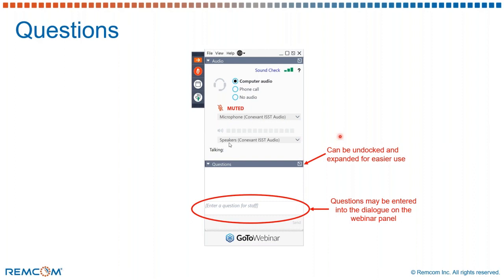So are there any drawbacks to using singularity correction? If you are particularly looking into drawbacks, I can check with our engineers on that, and maybe get back to you with more details related to that. But one of the things that I can let you know here is singularity correction would be more efficient if you're using that with high frequency simulations. But if you actually see, they perform in the same manner for applications in both low and high frequencies, but you would see more pronounced advantages of singularity correction for millimeter wave applications.